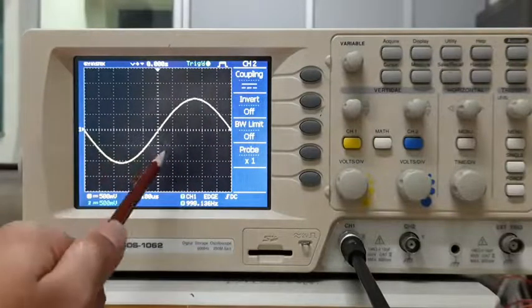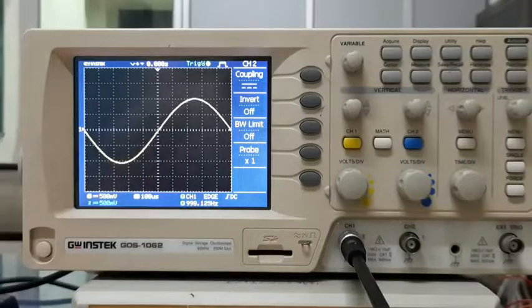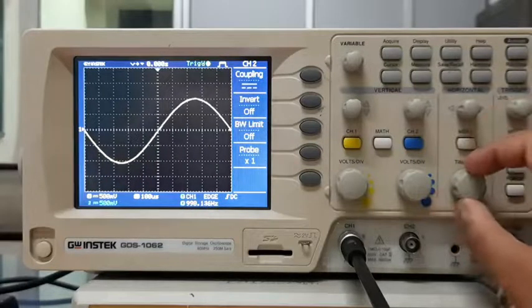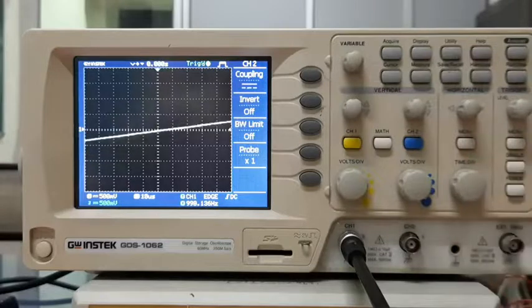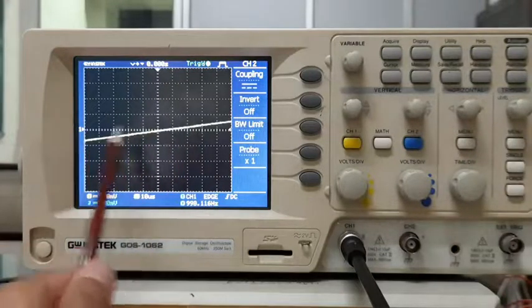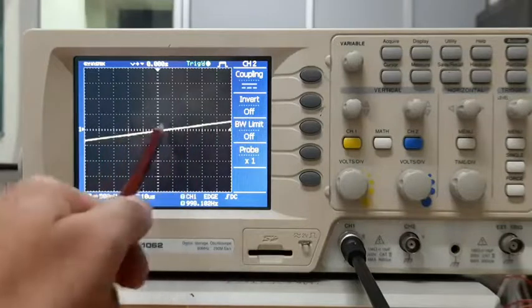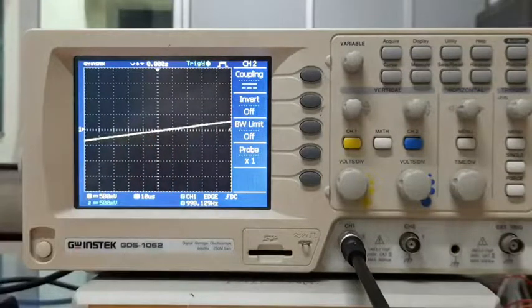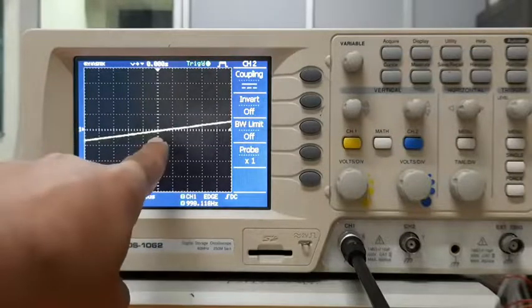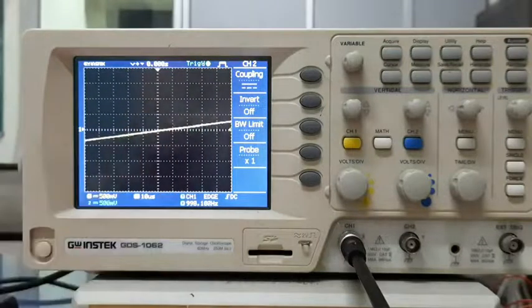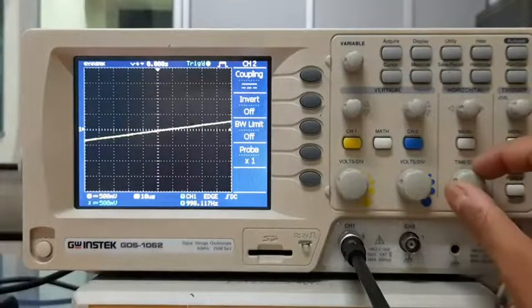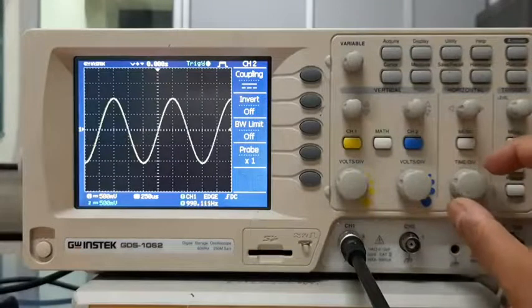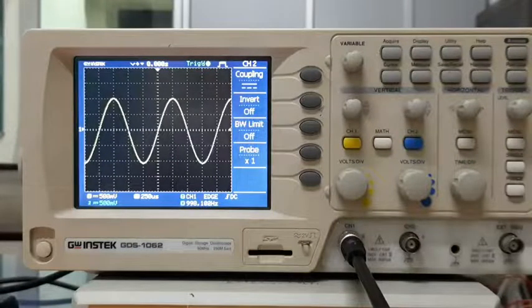And now suppose there is some interesting feature happening at the zero crossover point, then what you can do is you can change the time scale around here and then see that thing. So for example, now we are only looking at about 100 millisecond part of that zero crossover in the waveform. So whatever small features are happening here, in case my circuit develops such kind of signals, then we'll be able to monitor it and measure it more accurately. Okay, so let's just go back to 250 microsecond, and that gives me 2 cycles of this, right?